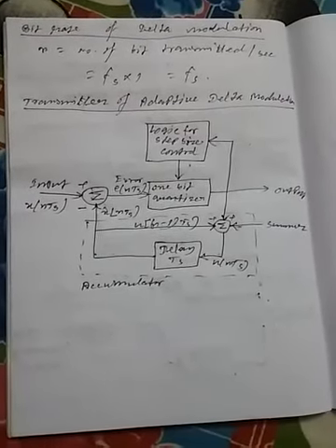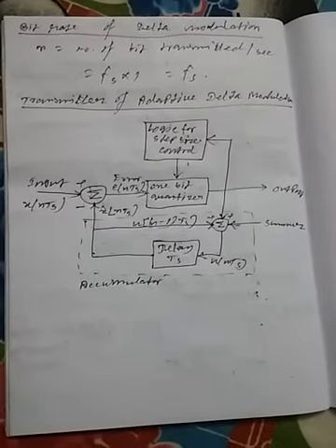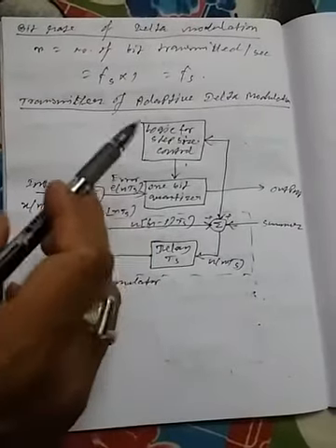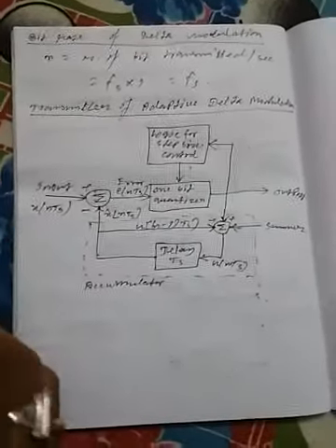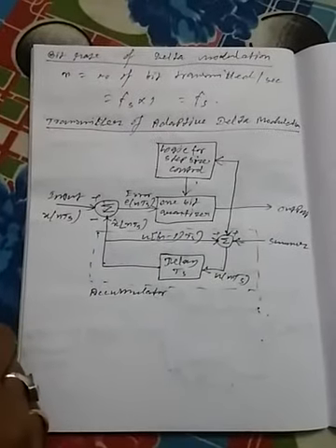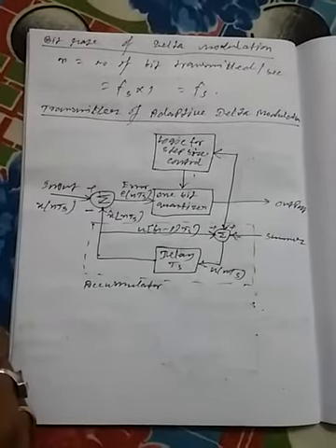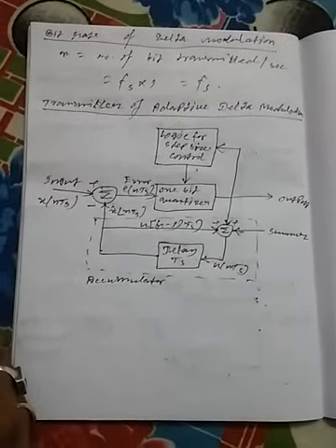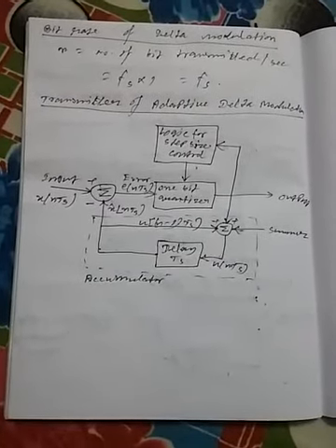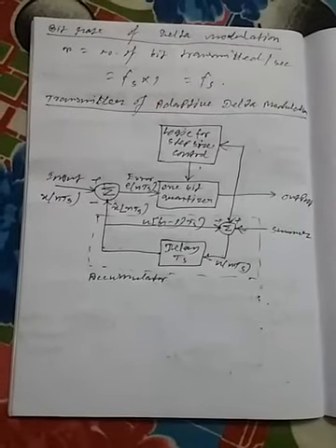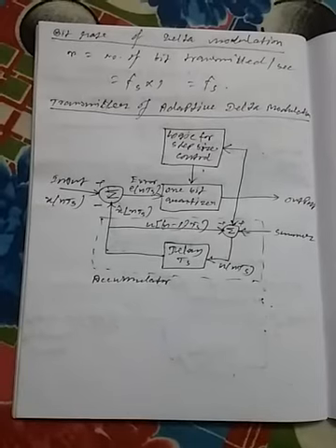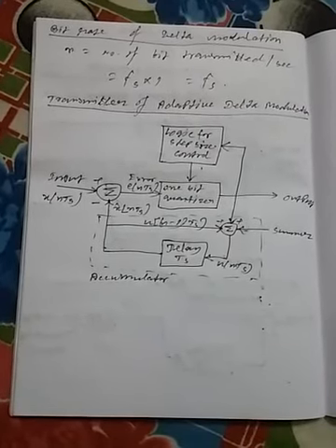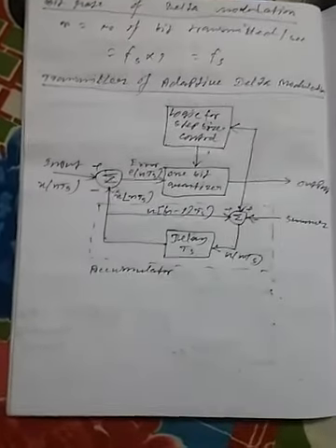This is the transmitter block diagram. The logic for step size control is added in this diagram, according to a specified rule depending on the 1 bit quantizer output. As an example, if the 1 bit quantizer output is high, then the step size may be doubled for the next sample. If the 1 bit quantizer output is low, then the step size may be reduced by 1 step.